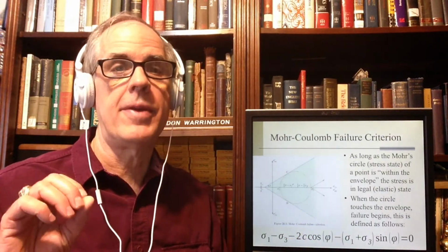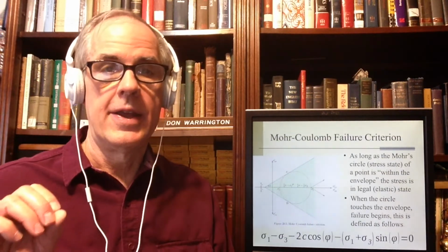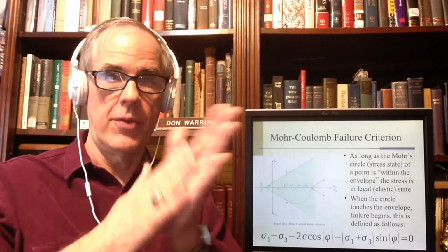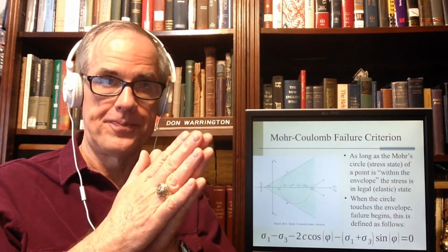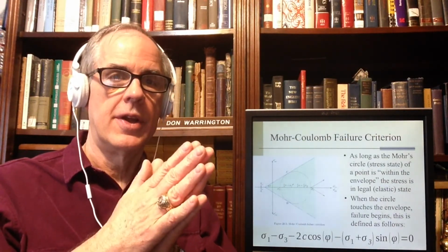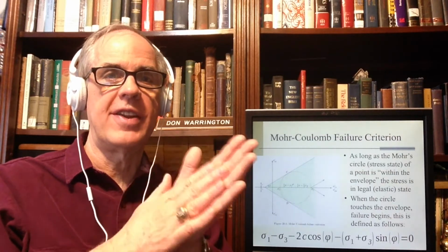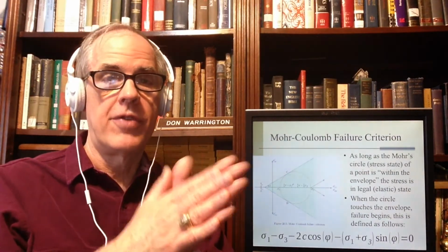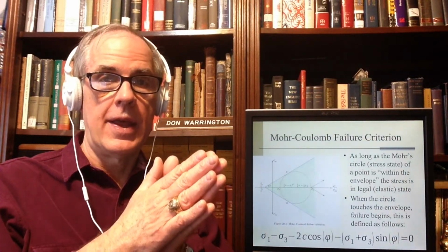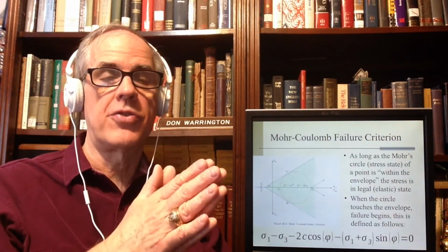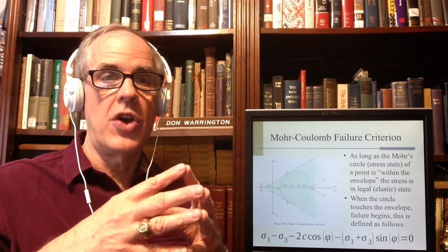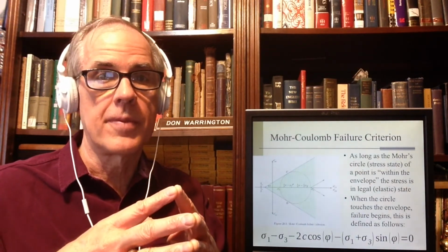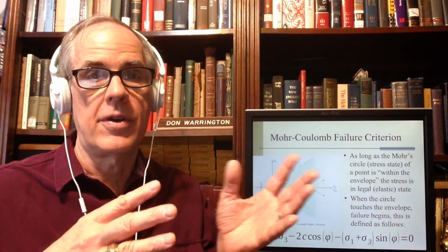By the way, phi, let me stop. Phi is the internal friction angle of the soil. The soils have their strength because the particles have friction against each other, not just against something else. And for purely cohesive soil, there is no strength in the soil if phi is 0 and C is 0.